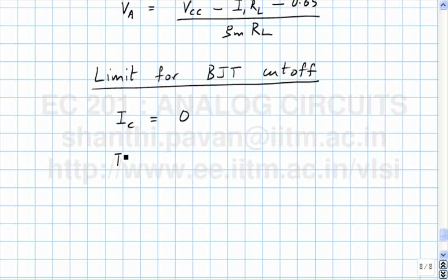It is the quiescent current I1 plus Gm Vs, and that is VA sin omega t, which means that VA is I1 by Gm. Now what is Gm? Gm is IC by Vt. Okay, so this cutoff limit is